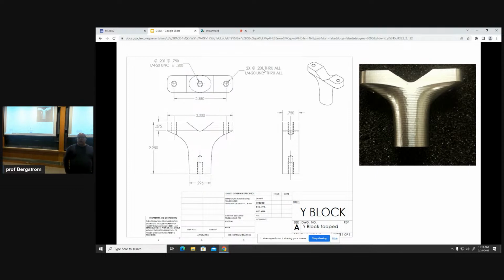for each tool? There are some rules of thumb that you can find, that different manufacturing processes can generally achieve specific tolerance bands or tolerance ranges. So yeah, there is, and it's within the band of our CNC machines for sure. The reason I picked plus or minus 5 is because I was being lazy. No other reason. I knew the machines could make plus or minus 5 pretty easily. Knew our measurement tools could measure plus or minus 5 pretty easily.